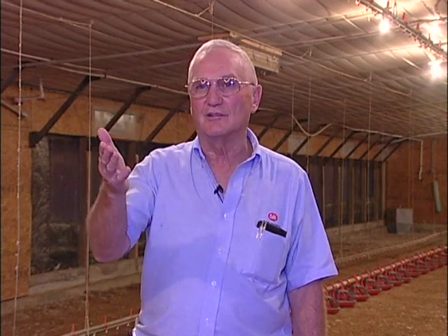So the highest pressure that we want to use in any chicken house is what it takes to get the air to the center of the house. Now, when we talk about the pressure that we rate fans at, for example, there are 4 that we have to add together. It starts with the shutters and resistance through the house and through the pads and through the inlet curtain. So we only want to use the pressure that's necessary to get the air to the center of the house. That way we get by far the highest air volume and the best air distribution through the house.